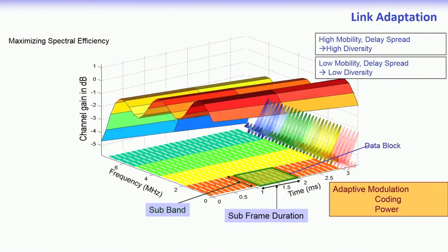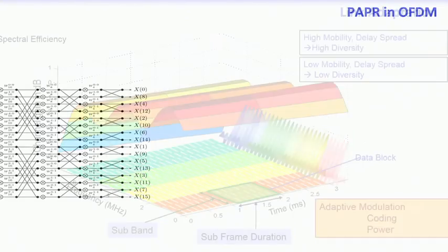This particular picture is also important in terms of the time frequency diagram, because whenever we are talking about the frame structure, the frame design, or any other thing, this picture should be available in mind. There is a time, there is a frequency, there is a group of symbols, and we have, as always, said this is the OFDM symbol duration, this particular part. This is the subcarrier bandwidth. So, the entire picture should be available in mind when we are discussing such things.